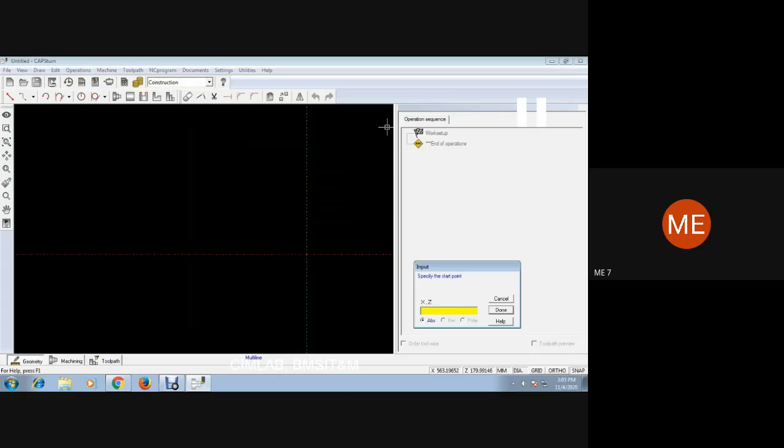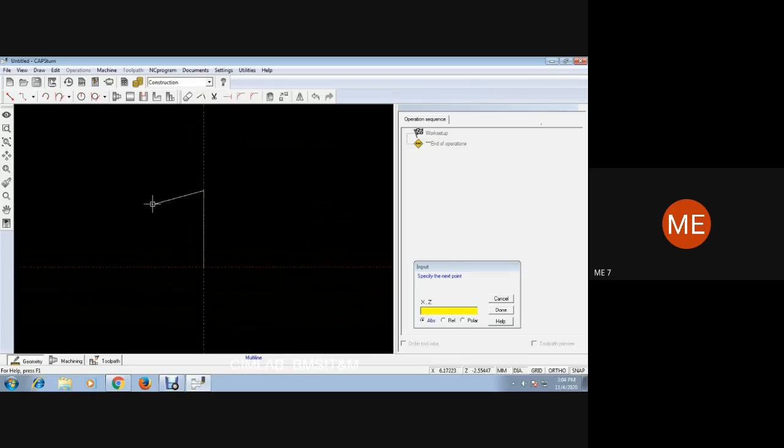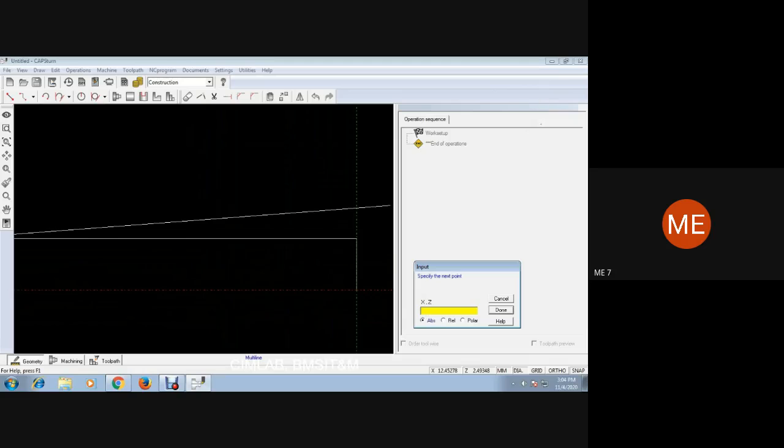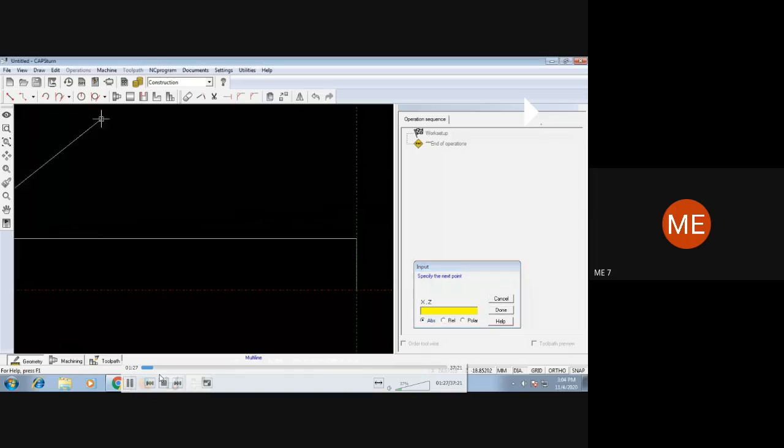Go to the multi-line option. We'll get this particular window over here. Enter the x and z coordinates. First 0, 0. Then we'll draw a line vertically, in the upward direction. Then the diameter is going to be 7.5, and for the next coordinate 30. Sorry, the radius, because we are drawing only one half of it, and in the subsequent steps we can mirror it.